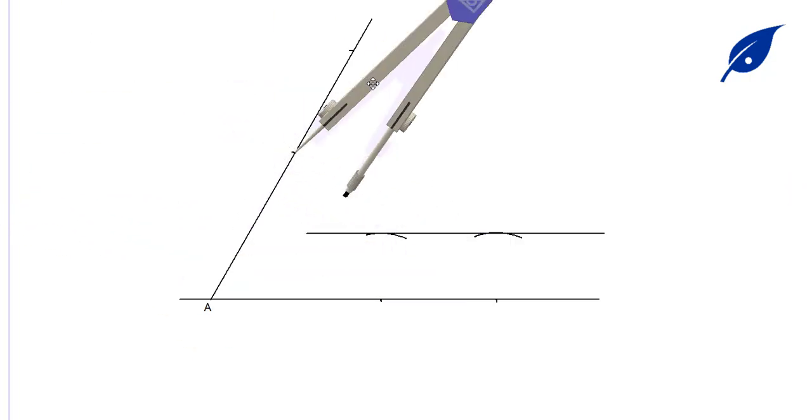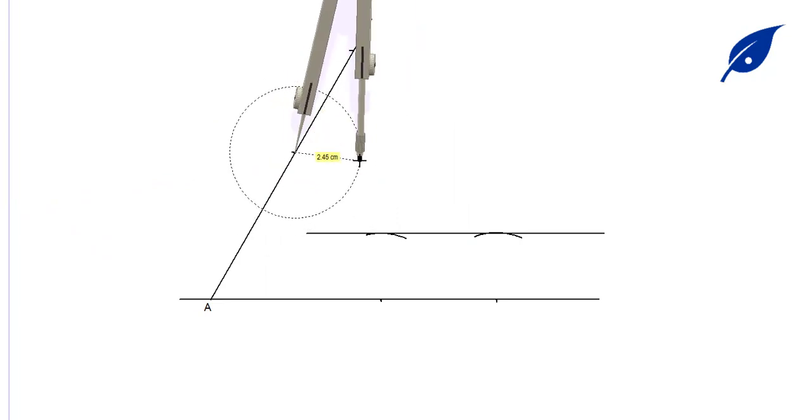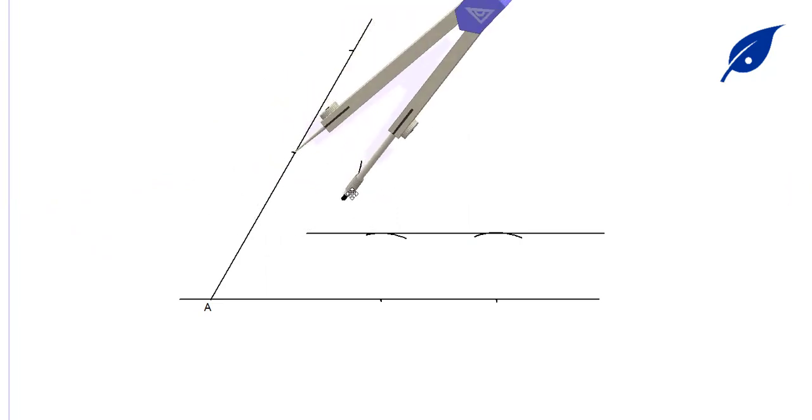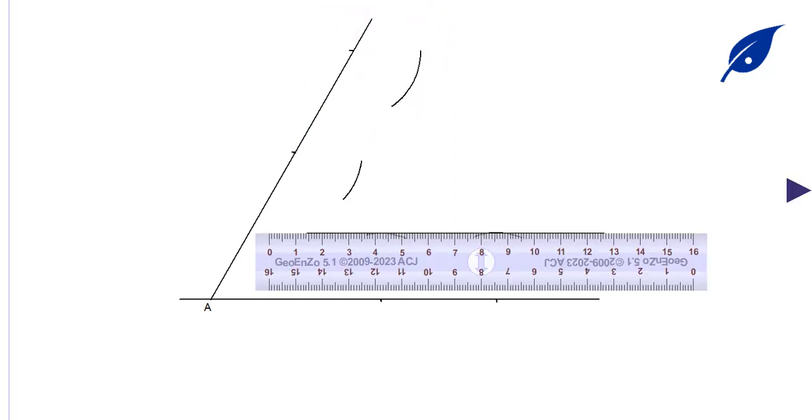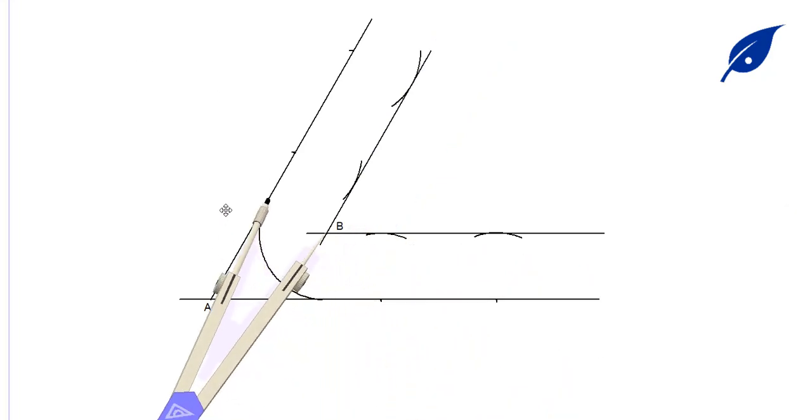Then we also duplicate the same for this other straight line, we produce the arc of radius 25 millimeters at this point. So we connect the lines. Where they meet, we call the point P. Now pick our radius 25 millimeter and the center at P. We describe the arc. So we have the required arc at this point.